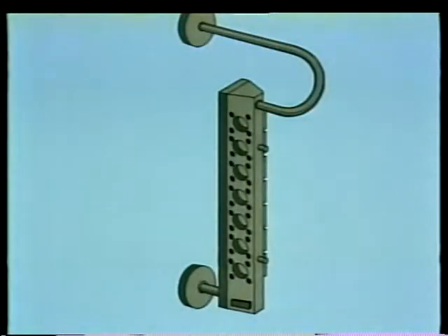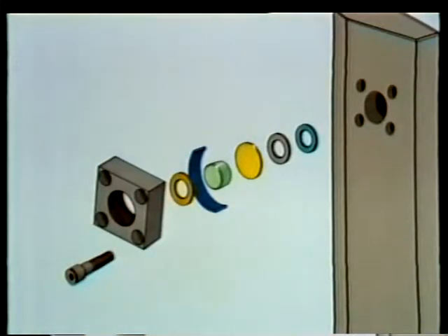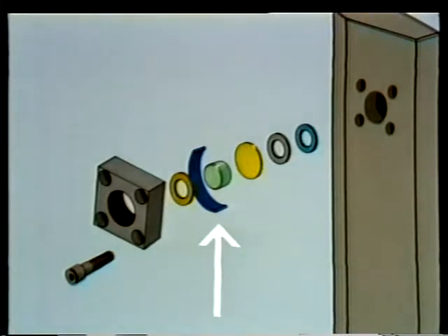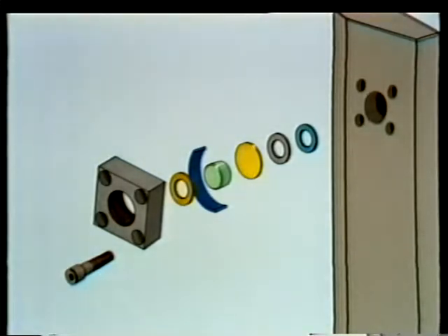The gauge we'll be working on consists of a gauge body and a number of ports, each of which includes the following parts: a sealing gasket, a protective gasket, mica, packing strip, glass port, cushion gasket, cover plate, and cap screws. These are the parts you'll be seeing as the gauge is disassembled. For our demonstration, we've used two multiple port gauges that are slightly different but contain the same parts.